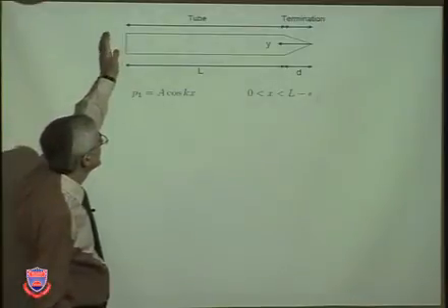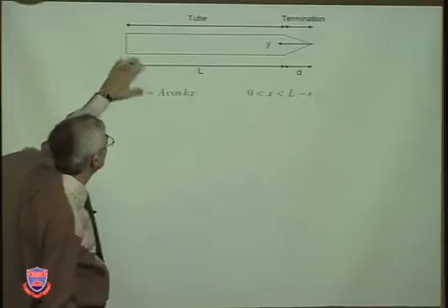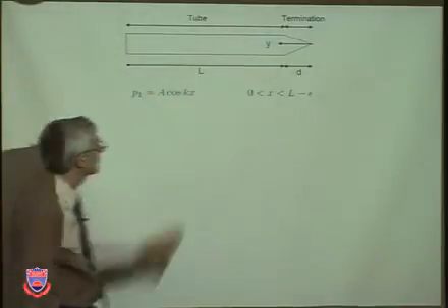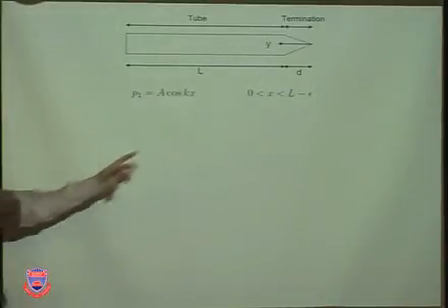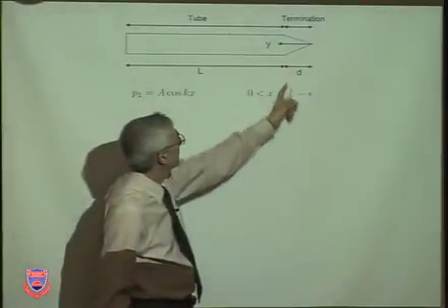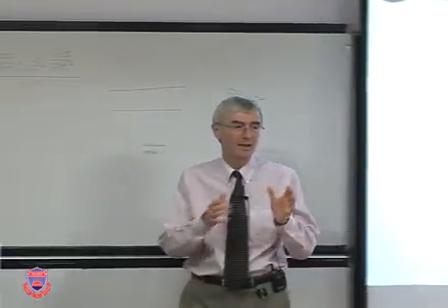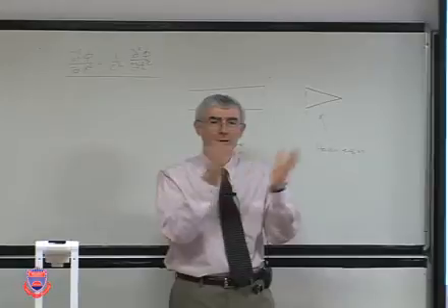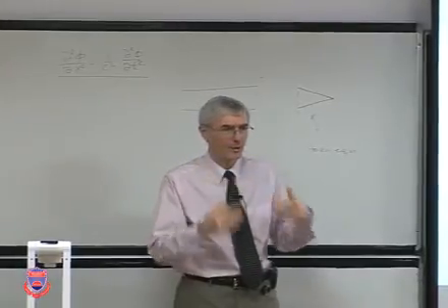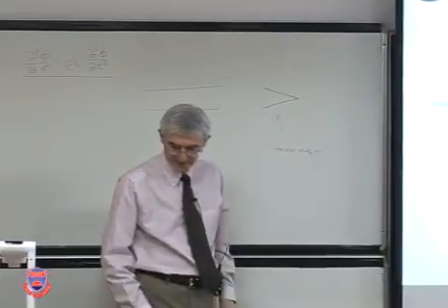This is the tubular part where pressure 1 is in terms of the x variable, cosine kx, between 0 and L minus epsilon, just before it gets to the interface where they meet, only because their acoustic field is not quite uniform. To be technically correct, we say L minus epsilon.